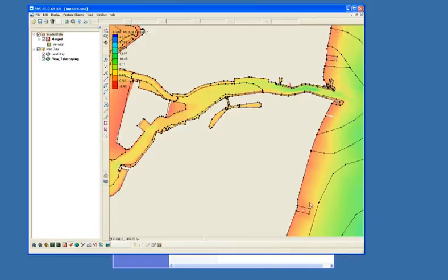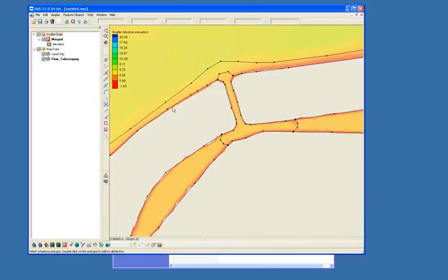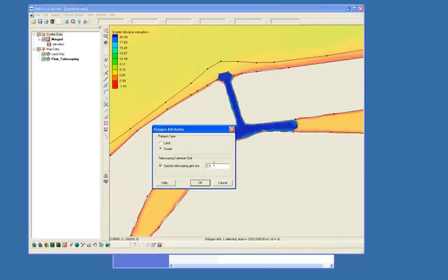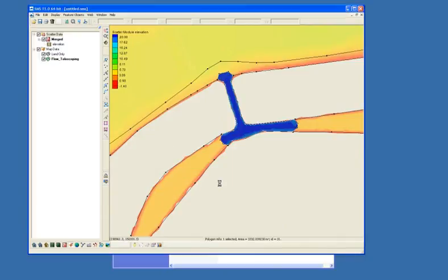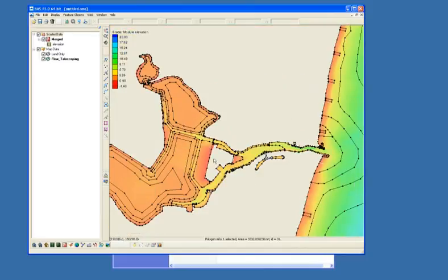You see that each one of these groin fields is represented. The jetties are represented. The spacing in this area is now 2 meter spacing so that we have adequate bathymetry through here. Spacing through there. And so you just keep iterating until you're comfortable with what that map file generated as far as the grid.